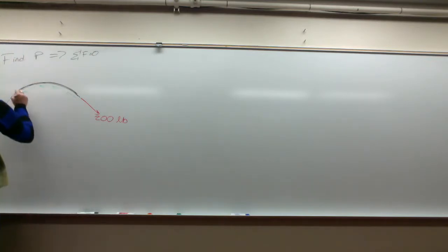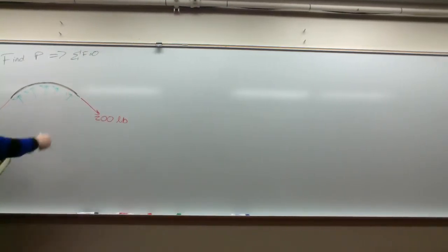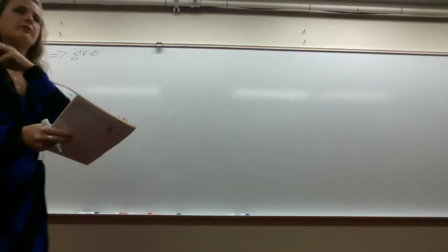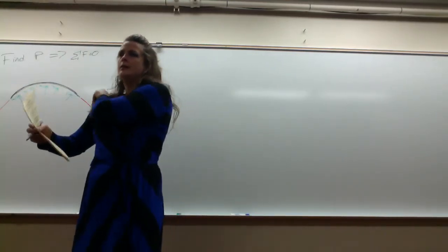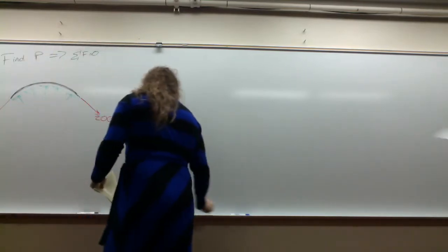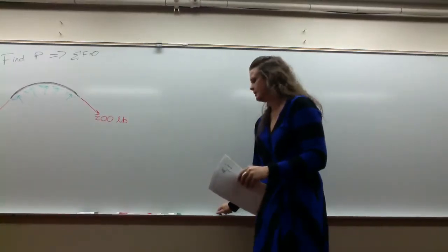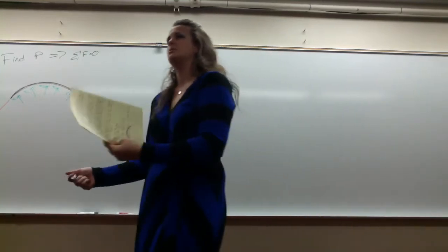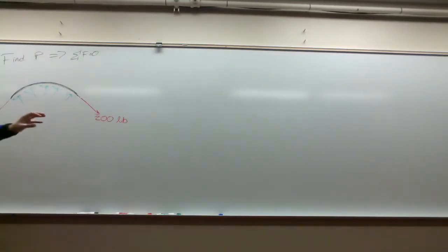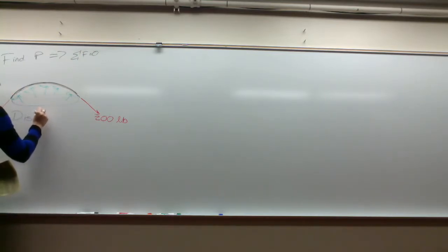So we have our normal force. There's a contact between the pulley and the rope. The rope is applying a normal force onto the surface of the pulley. What kind of loading condition, think way back to our second module, is this? Yeah, it's a distributed load. This loading condition is a distributed load.